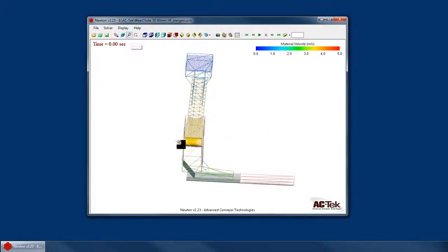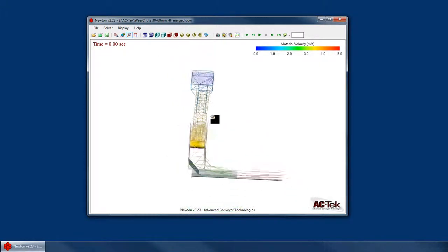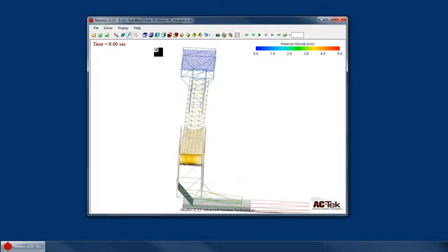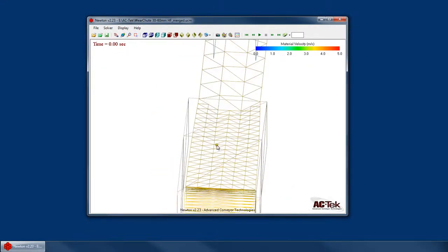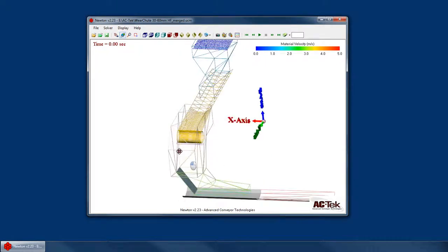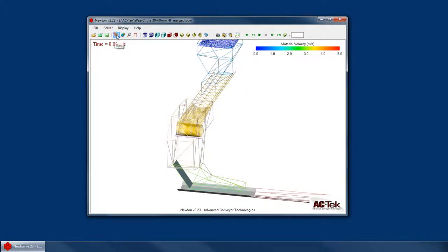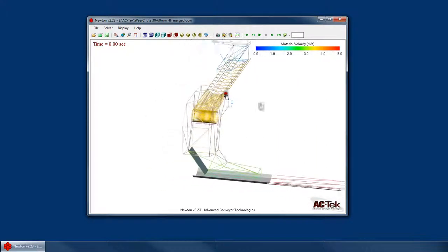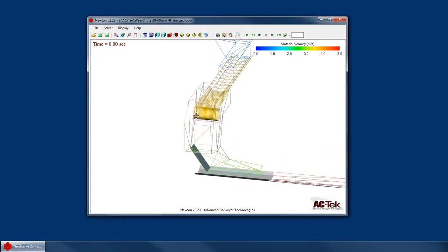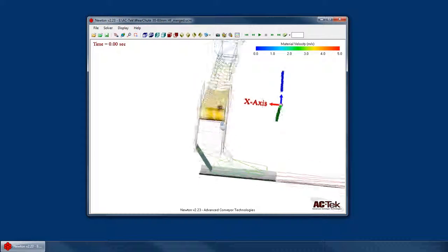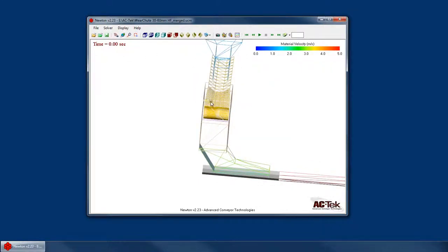And then we have the ability to zoom. You can also zoom using just the mouse wheel if you want. And then zoom window, where you can select a window to zoom in on. And I should also mention that in order to pan, you can either use the pan command, or you could simply hold Shift and click and move the mouse around. Similarly to orbit, you can hold Control, and it will switch you right into orbit mode without having to click those buttons.